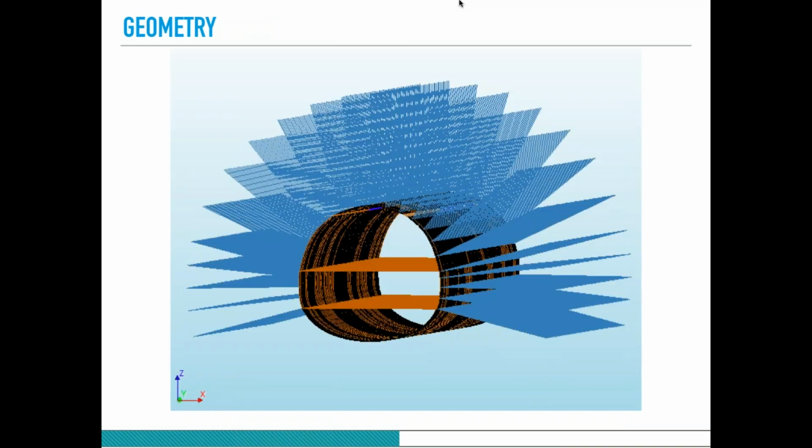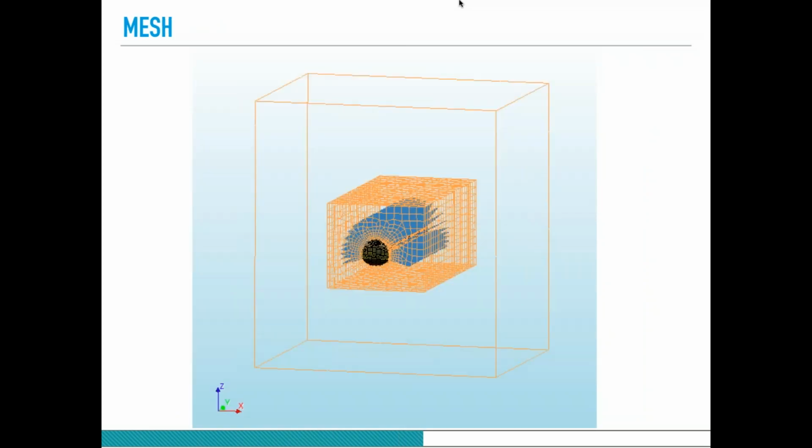This is also another view for the 80 meters, and I have divided the soil inside the tunnel into 3 parts so that I could excavate exactly the way it is excavated in reality. This is how I applied a cube around the tunnel to have a finer mesh, to have more precise results.